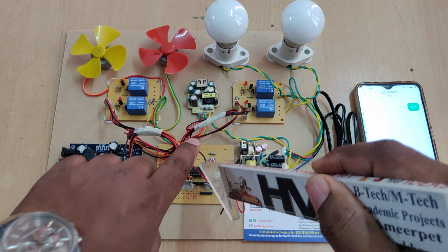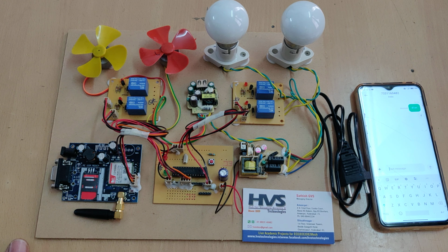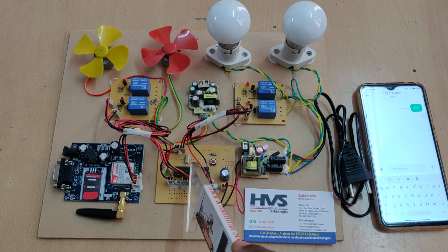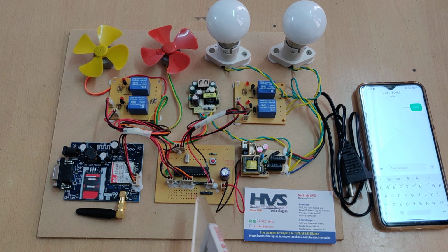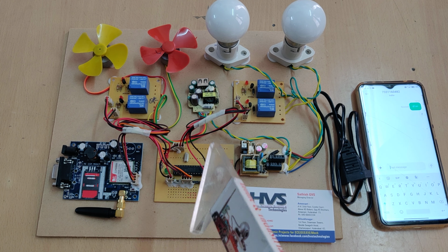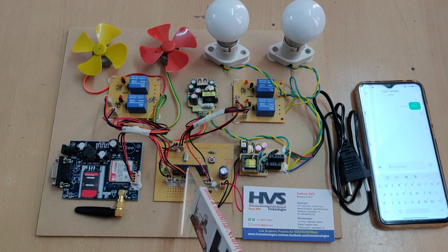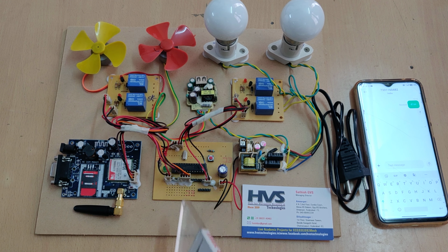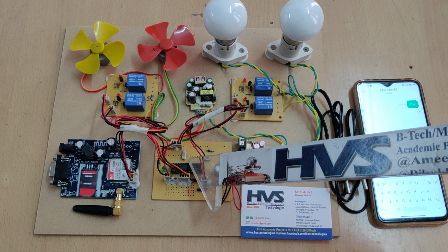And coming to this motherboard, this one is the restart switch with a 10 kilo ohm pull up resistor, and this steel plated one is a crystal oscillator which will provide the 20 megahertz oscillating frequency to the microcontroller. With the oscillating frequency, we have provided some set of instructions like reading SMS and controlling the output devices. This instruction will be executed at 1 clock pulse per instruction. We are providing 20 mega clock pulses per second, so the microcontroller will execute 20 mega instructions per second. That is the speed of our microcontroller.